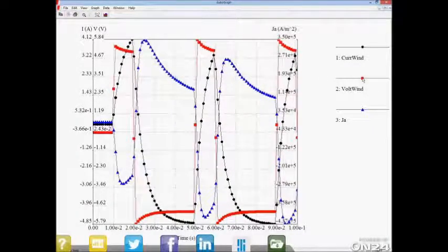If we look at the voltage on the winding, then again we start at 0. We've applied 5 volts, but the fact that the B field is changing in time means that we get an induced voltage on the coil as well. So it rises up, and then it decays down towards 5. Again, here you see it gets to 5.07 in the short time frame of the positive, but if we look at the negative, it's gone pretty much back to the -5 volts that was applied. Once again, you notice that the first pulse has a substantially different behavior than the following pulses.